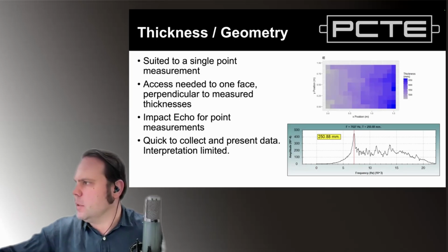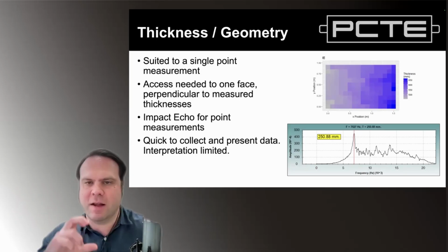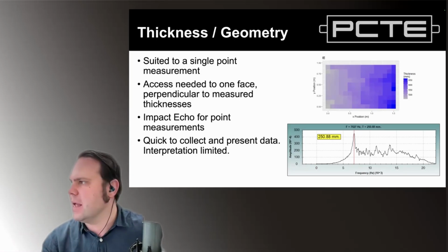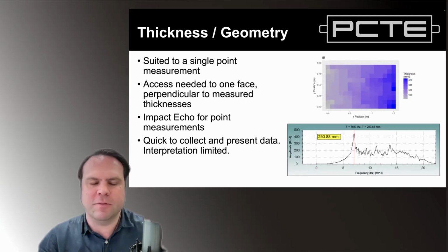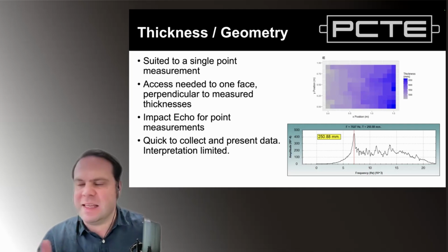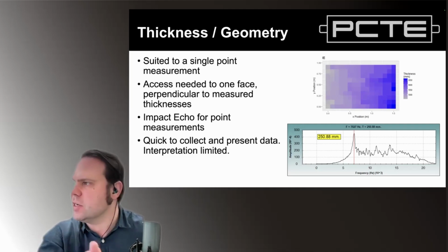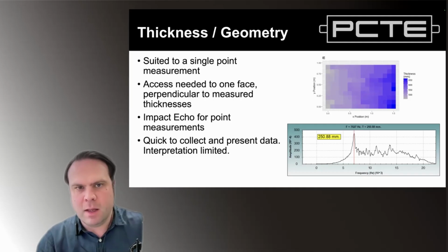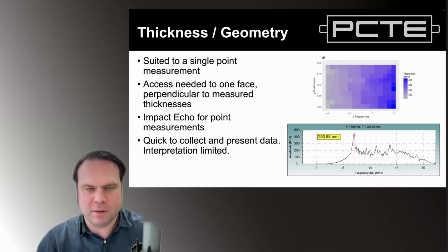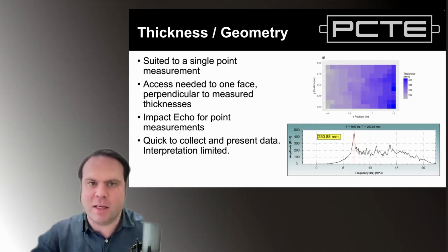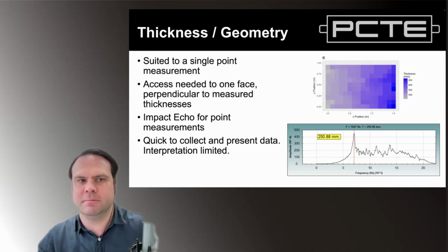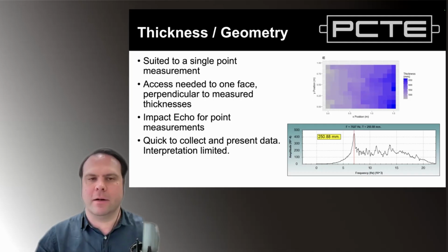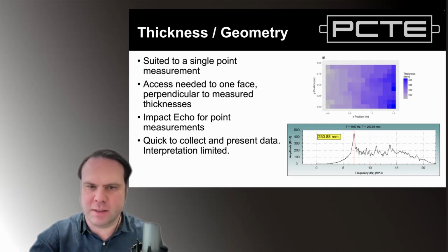In the example chart below, in this case, our thicknesses started around 0.5 meter and extended out to maybe 650 millimeters, so another 150 millimeters deeper. And we can see that we just had a very clean shift to a lower frequency to the left of the chart, so a thicker element from the left of that boat ramp slab to the right. And the data was done on a grid just to make the visualization easy for this example.